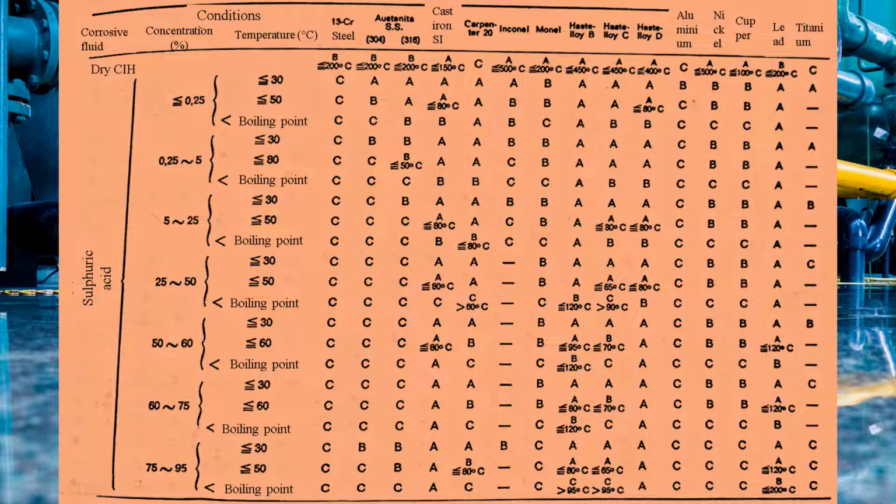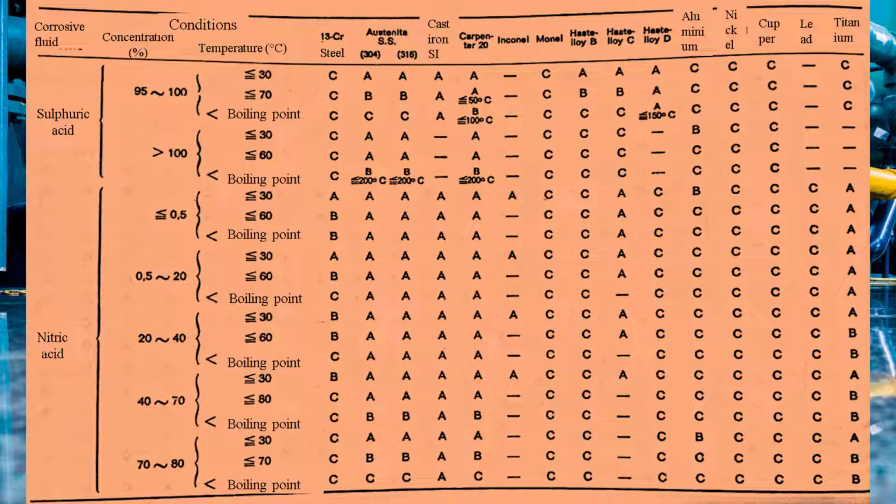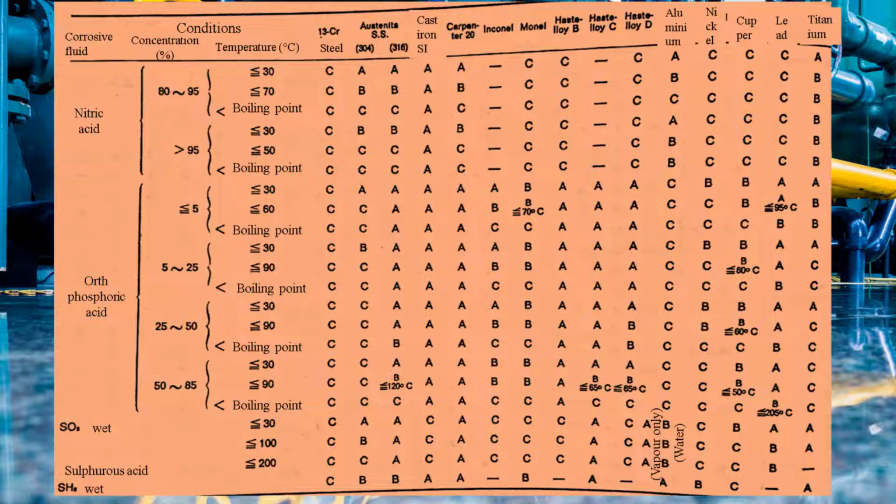Where corrosion-resistant material is expensive or unsuitable, lining materials such as plastics, fluorocarbons, elastomers, glass, lead, and tantalum can be used. But if the lining fails, the fluid will attack the base metal, and the valve will be punctured.